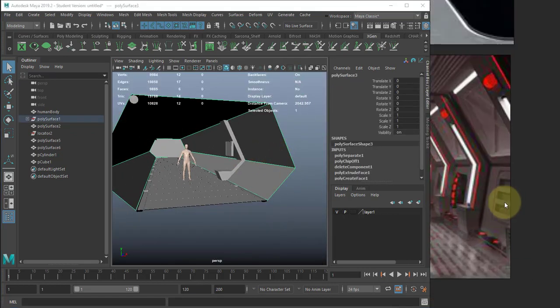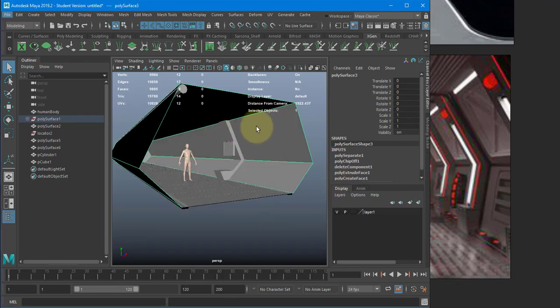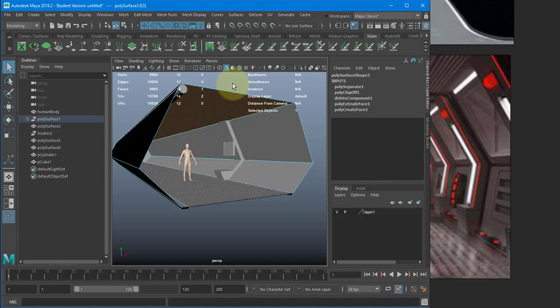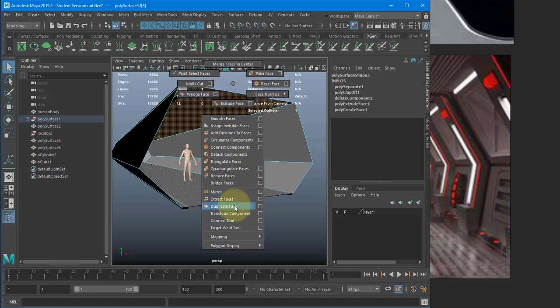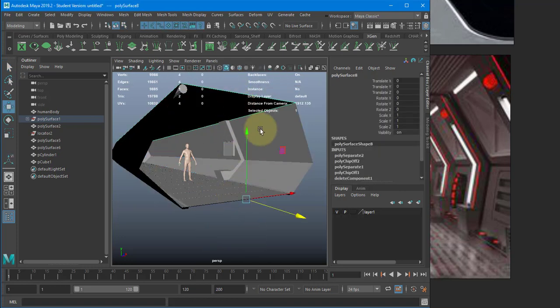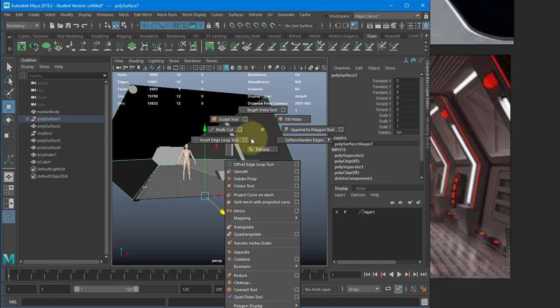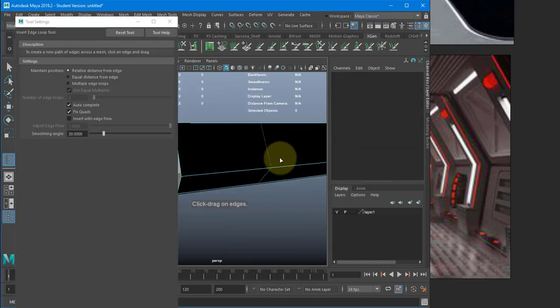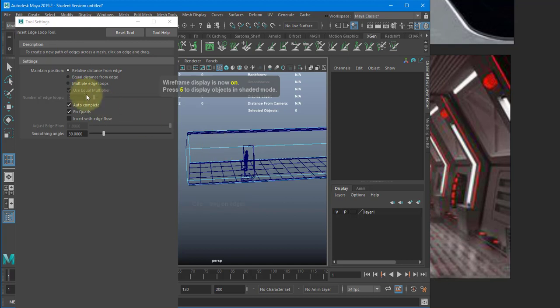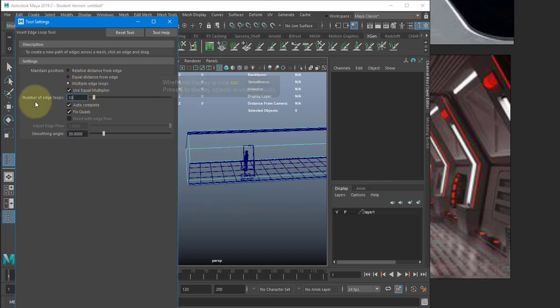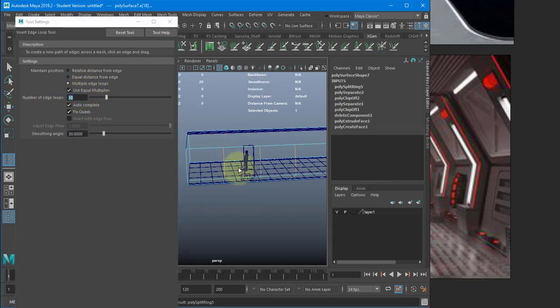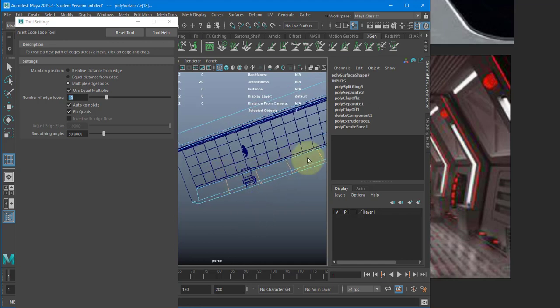I like these. There's little doors. It's kind of hard to see, but there's little like doorways there. So I think I'm going to divide this up even further. So let me break the ceiling off. So I'm just going to extract that. I'm going to go to my edge loop. I'm going to add in some divisions here. Let's say 10. I'll get these kind of synced up with the ground divisions.